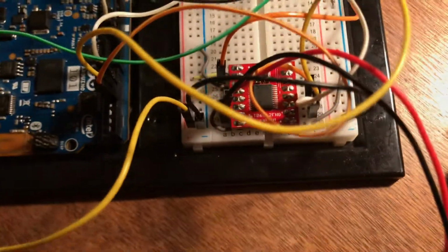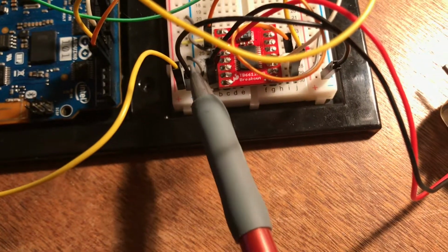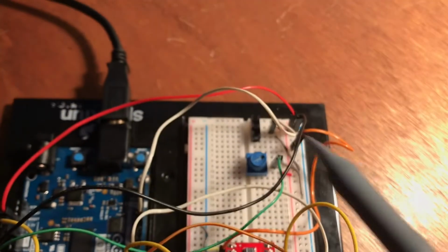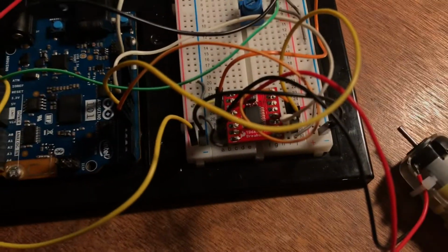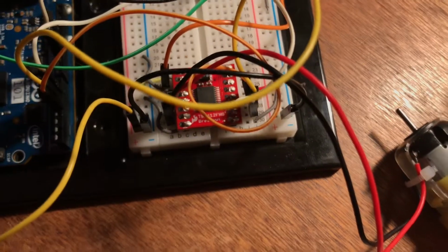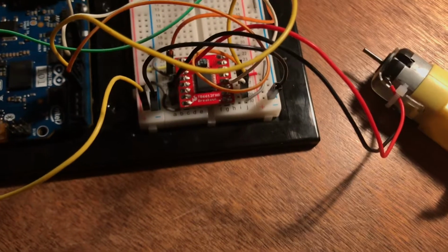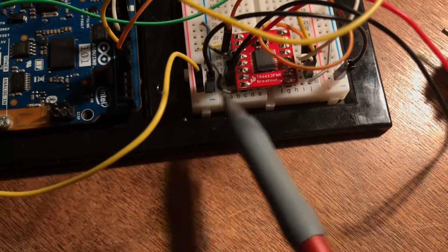Then this gray cable right here is grounding the board that I connected to the negative column through this black wire, and that negative column to this other black wire here. Then we go to the red wire attached to the motor that attaches to the pin BO2 on the board, which is a motor B connection, and the same with the black wire that connects pin BO1, which is another motor B connection. And then this gray wire also grounds the board.